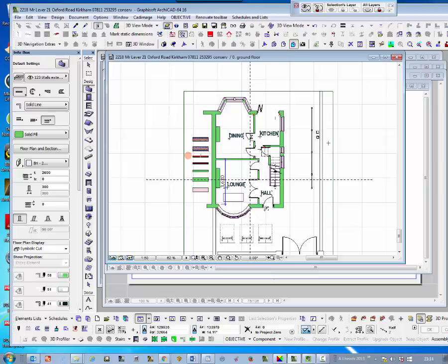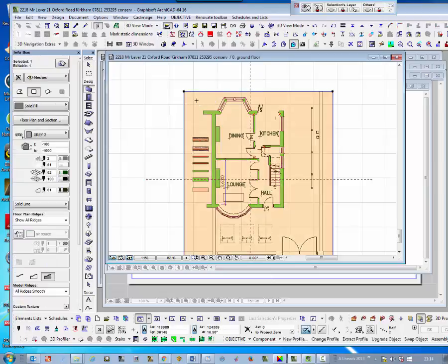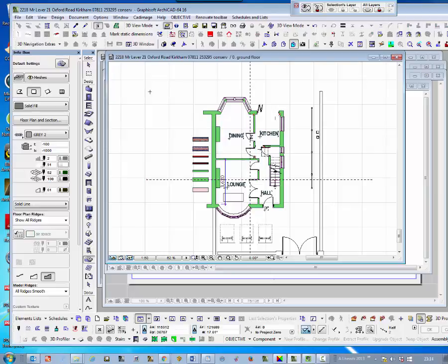Now the back of this property doesn't have a bay, and what I'm going to do is alt click on that. That is the ground level outside. I've alt clicked on it to take it to the cursor as a default, and I'm going to delete that now, and so that I can get at it later on, I'm just going to put that in that corner. So for later on we'll be able to use that to get back and put the ground on the outside.